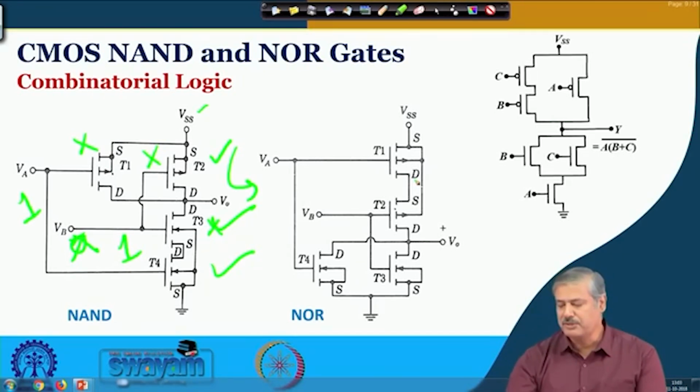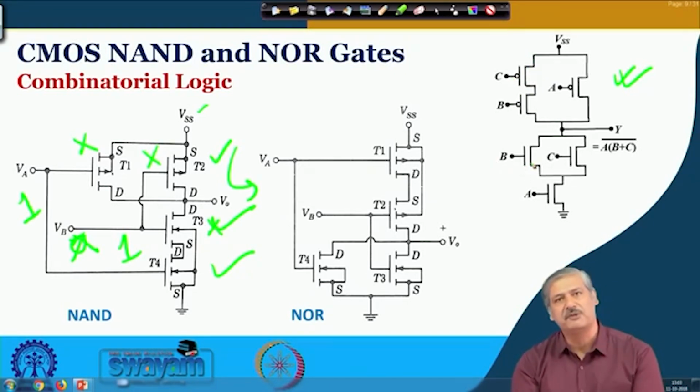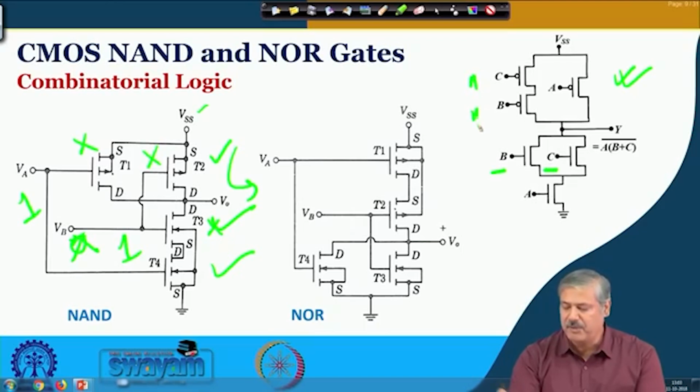So, this is also something by which drawing becomes a bit easier. So, this presence of bubble over here actually signifies PMOS. So, this is the symbol of a PMOS in that fashion, and this is the symbol of an NMOS, absence of this. Okay. So, these two are in parallel and corresponding these two are in series. This is in series with the other one. So, the whole of it, what corresponds to B and C, what corresponds to B and C, okay, in PMOS, right.